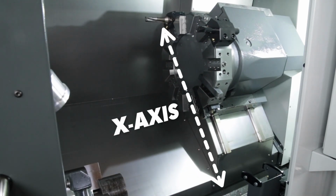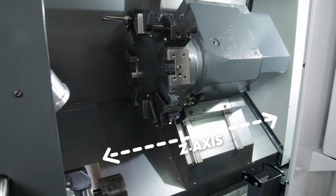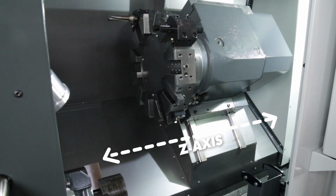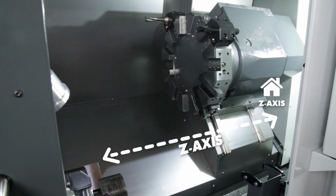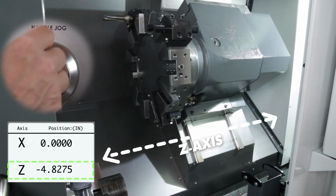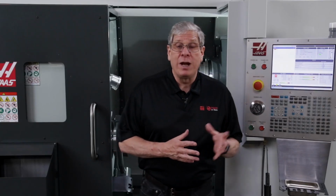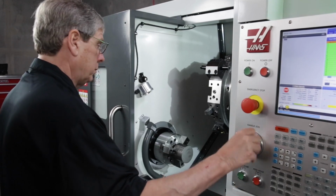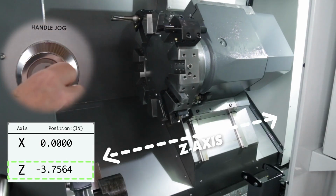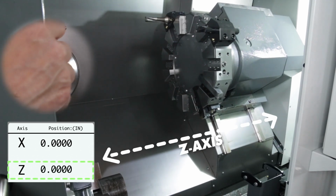The machine coordinate system defines where the axes can move, and it's how we measure how far they've moved. It basically tells the control where the turret is inside the machine. On most lathes, home position for the Z-axis is here, on the far right side. As the turret moves away from this position, you can see that the Z-axis position readout is getting more and more negative. We can say that we're moving in the negative direction. If we stop here in the middle of travel and start going back the other way, we can see the position readout is now getting less negative. Now we're moving in the positive direction.